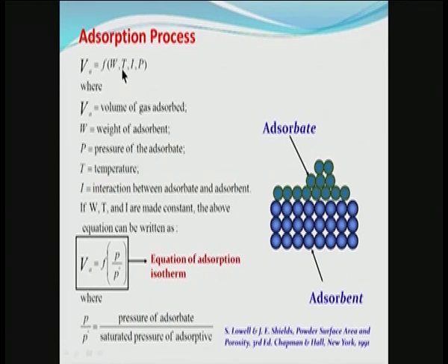As we noted, high temperature actually does not facilitate adsorption, it actually facilitates desorption. So, temperature is important. It depends on the interaction between the adsorbate and adsorbent, and it depends on the pressure of the adsorbate over here, how much pressure in the vapor phase is exerted on the surface that adsorbs.